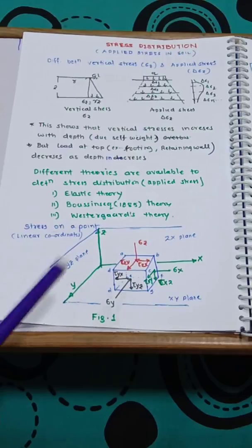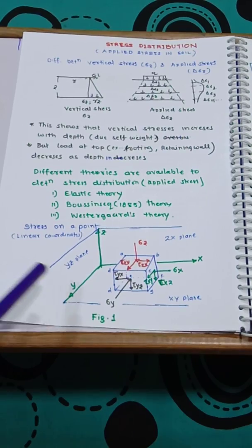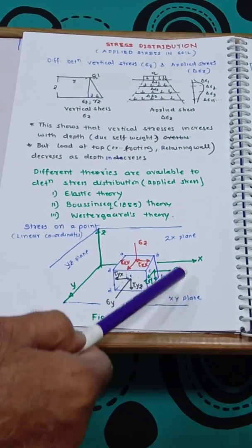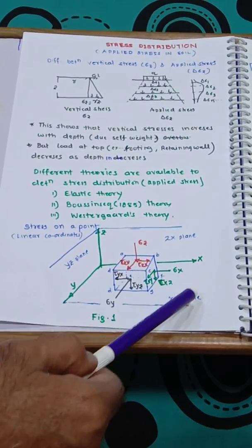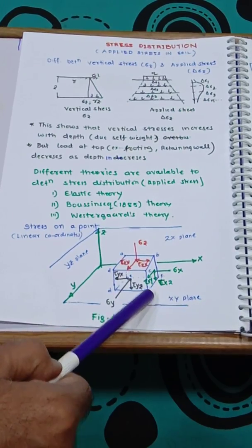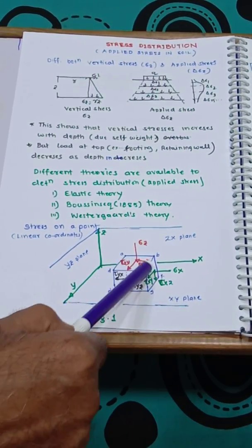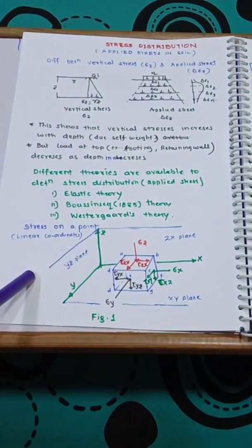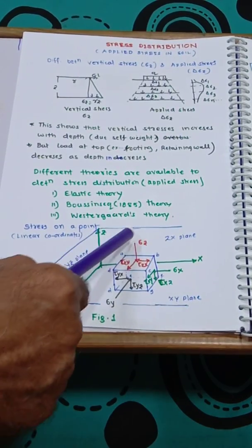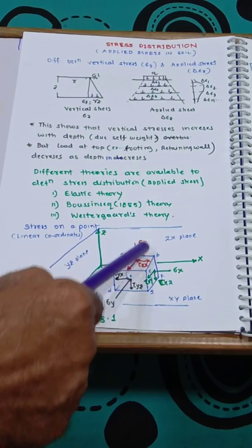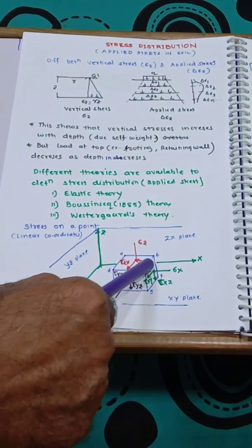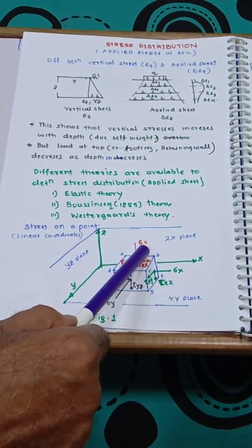Now how are the stresses designated? So the first and most important thing to designate the stresses is the plane. Let us see, ABCD is one plane, which is a horizontal plane, and you can see CB, FG is a vertical plane. Now this plane is at a distance, if you see the perpendicular distance, this is also one plane. Like x and y, the perpendicular distance between these two planes is z. It is parallel to the z direction. So therefore for the stresses on this plane, the first letter is designated by z.